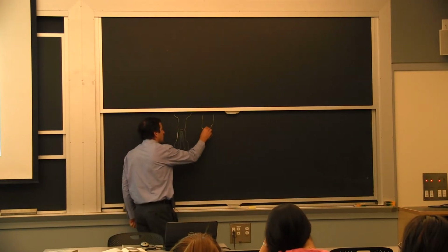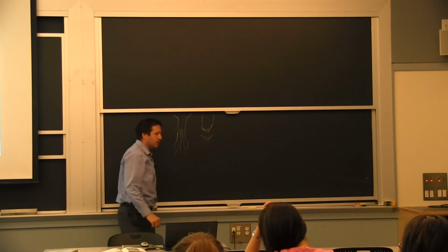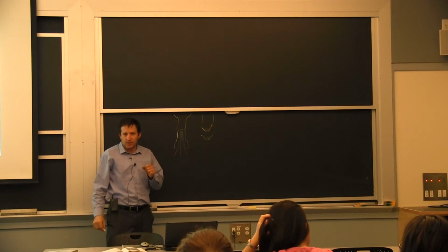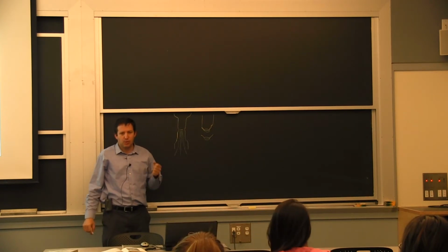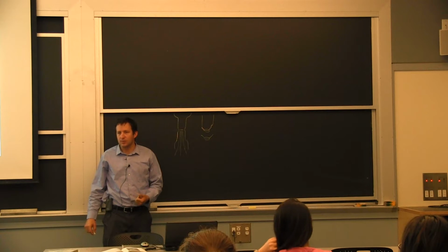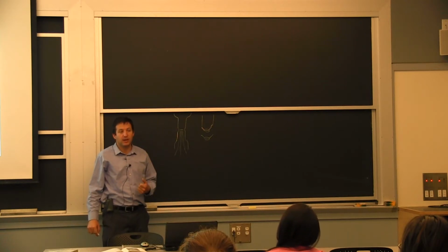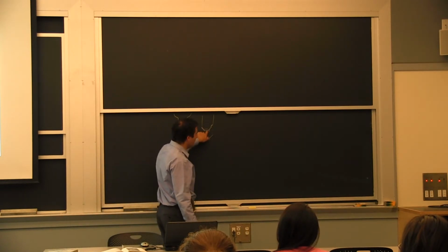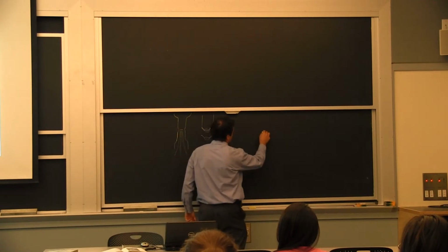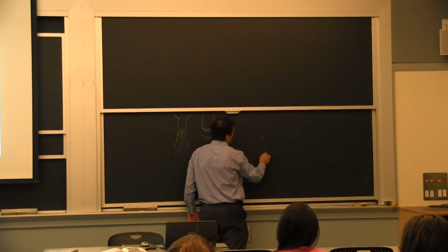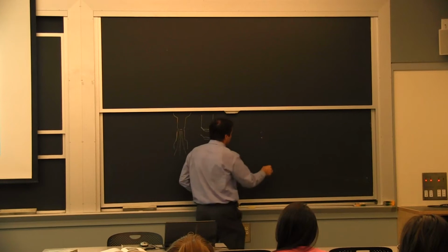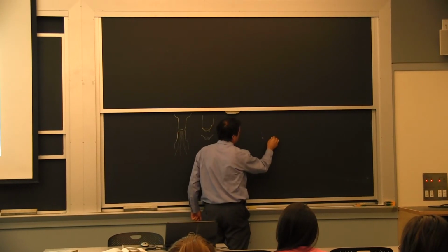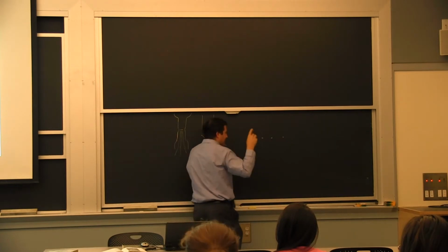So the reason why the crack starts here is tension. And you can have the most ductile material you can think of. The way it's going to break is by formation of microvoids, ultimately. So if we're looking in detail at what happens here at the initiation, say I had a little inclusion, which I always do, or even I had a grain boundary, or I had something that was not regular in my microstructure. So these are anomalies.